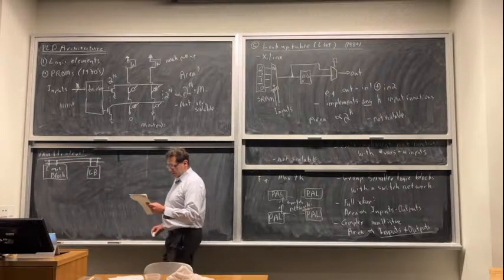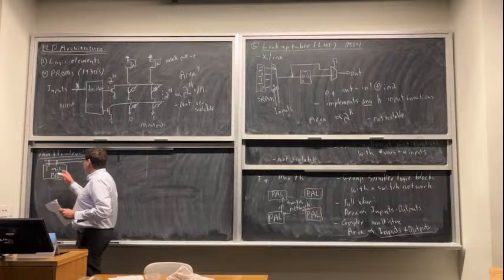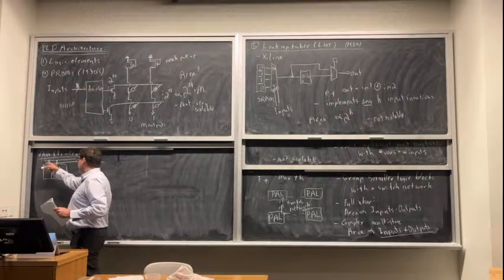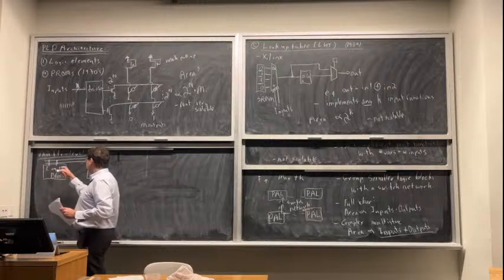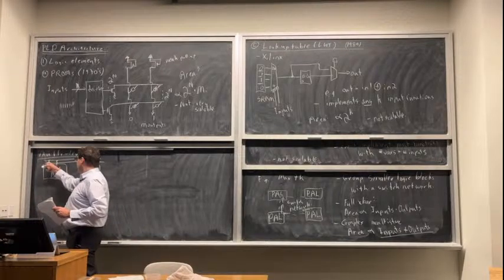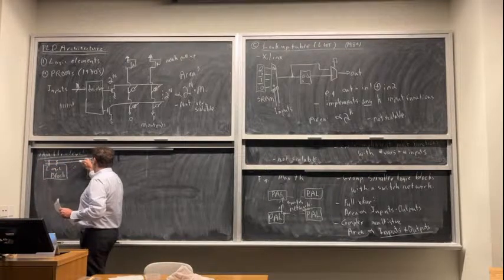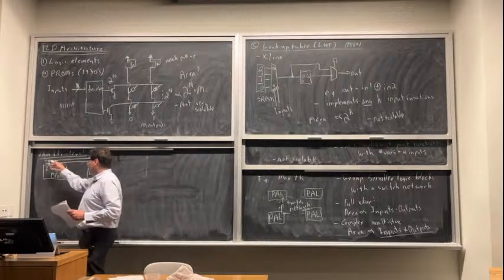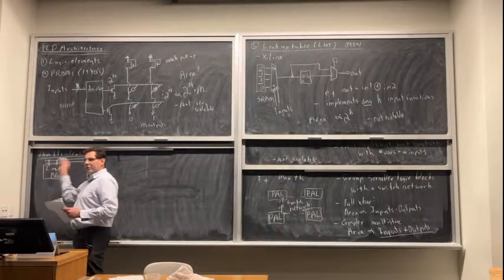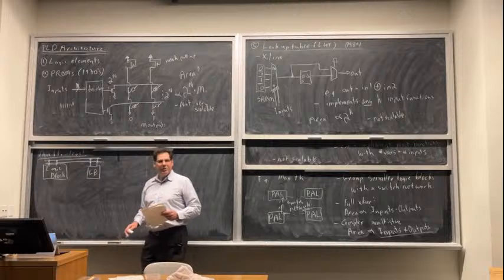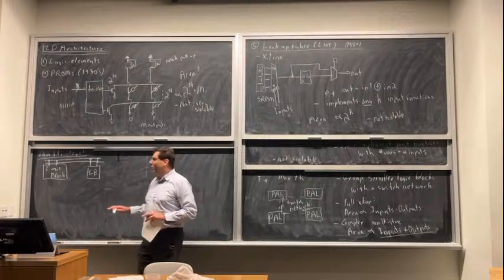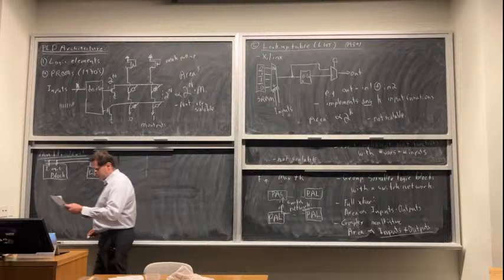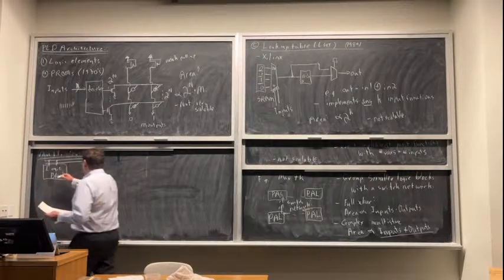I want to be able to programmably connect them. Let's say they each have 1 output. So I just make 2 routing wires, and I make programmable switches that let me connect the input and output of this block and the input and output of this block to those wires. And my CAD tools can figure out which switches to turn on, so these things can talk to each other no matter what. Probably I'd have more than 1 input and 1 output, but I'm just keeping it simple. So I only need a couple of wires. So that connects 2 logic blocks.